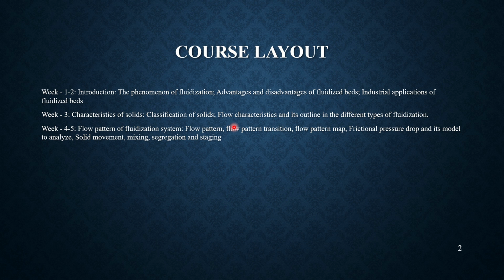Week 4 to 5 we dealt with flow pattern of fluidization system, flow pattern transition, flow pattern map, frictional pressure drop and its model to analyze solid movement, mixing and segregation and staging. So when we are passing the fluid inside the bed, as we mentioned, it is above a certain velocity requirement. Does the fluidization phenomenon remain the same irrespective of the velocity? No. With respect to the inlet velocity, the fluidization phenomenon is different.